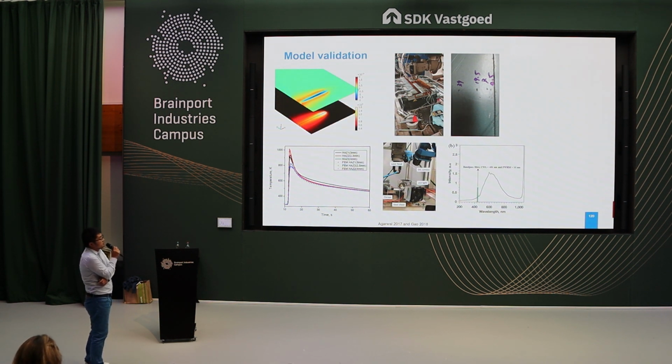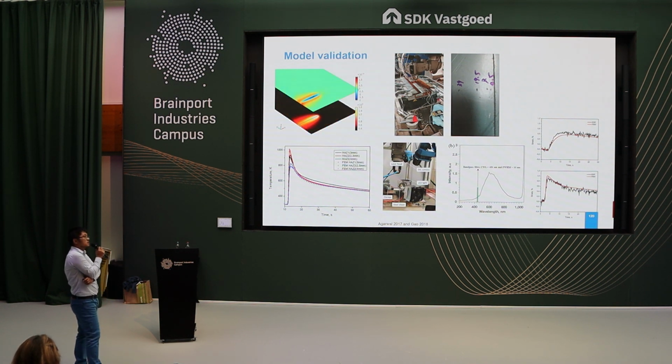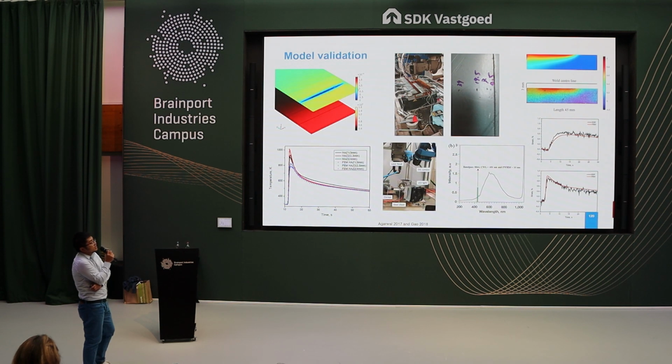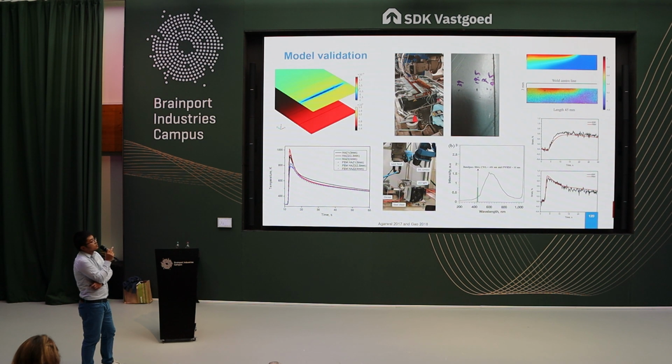With that, we can manage to measure the in-situ strain during welding, and we can also compare the experiment with the simulated results. There are two images: one is far away from the weld, one is close to the fusion area. It's a very good validation as a function of time. And we have also chosen a time instance where the laser is somewhere in the middle of the weld to compare the strain distribution. So basically we are satisfied with this validation.